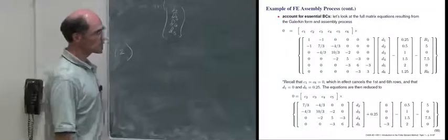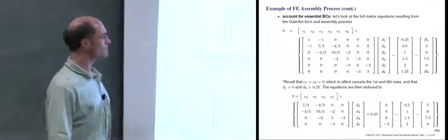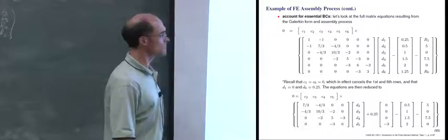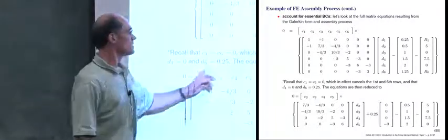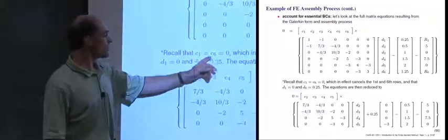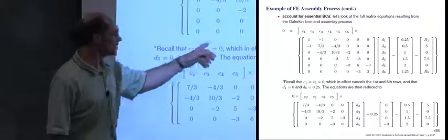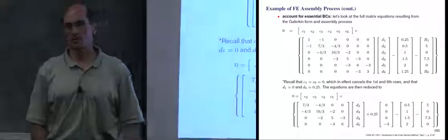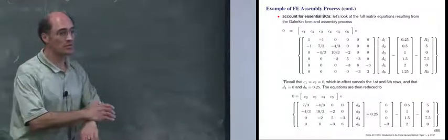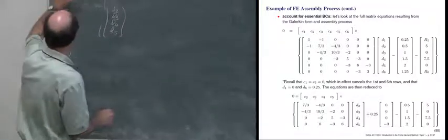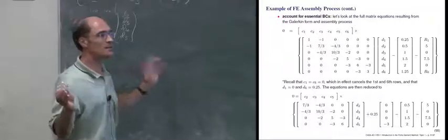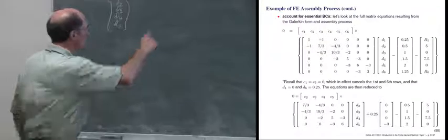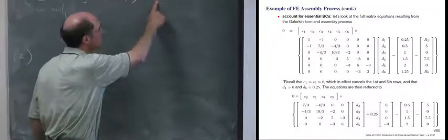There's this important concept from energy methods, which also applies in variational principles: where the essential boundary condition is prescribed, these must be 0. But everywhere else, they must be arbitrary. They're perturbations. So in theory, C2, 3, 4, and 5 can be anything. They're arbitrary. But this equation must be equal to 0.